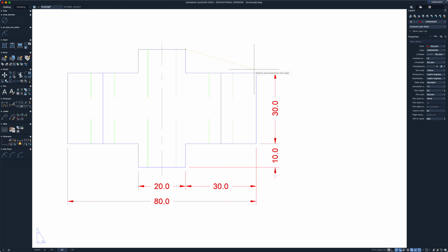So I'm for sure on the end point, and I can move out to this spot that's 10, click, and done. Now again, I can go get an overall dimension from here to here, which should be 50. And again, if we're going to follow the same setup that we did down here, it was 8 millimeters down. So what do I use again? The from command. So FROM, and from that point going in that direction 8, and there it gets set.